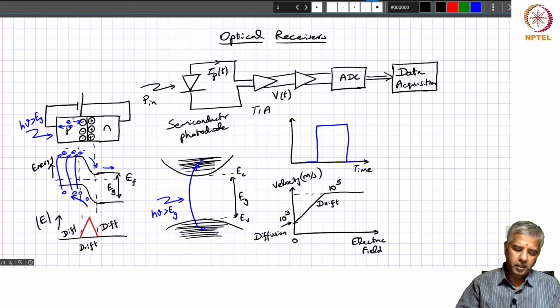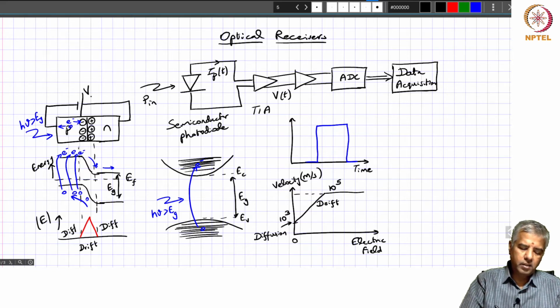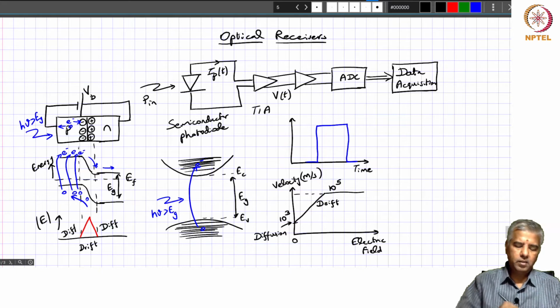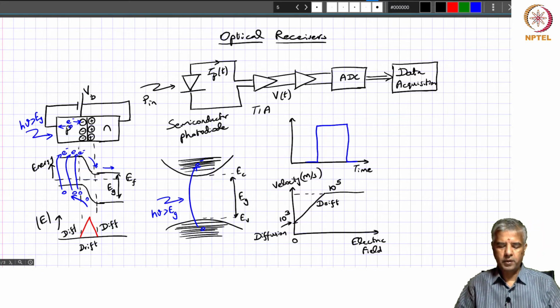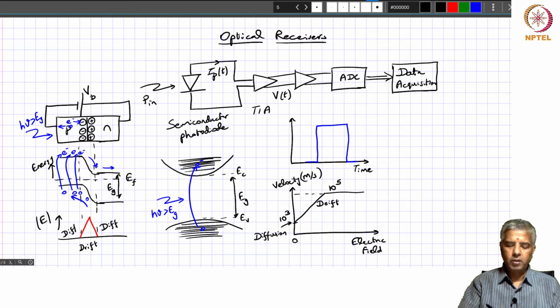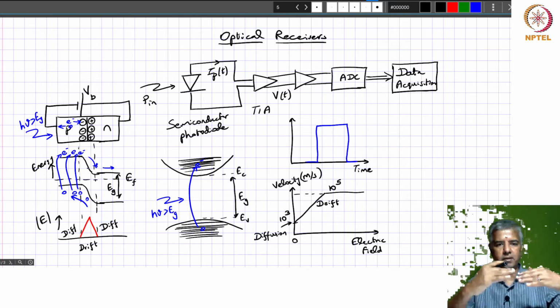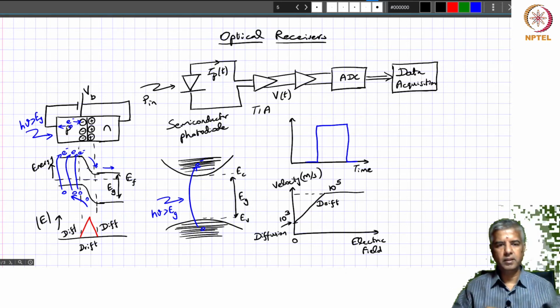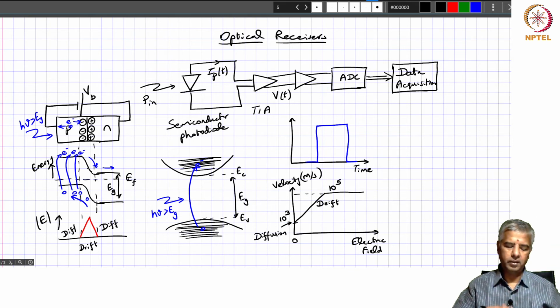And the key point here is, if you change your external bias, let's say this is VB, right? It's a negative bias, or a reverse bias, that we are providing. If you increase your reverse bias, then this electric field gets enhanced. Essentially, the Fermi energies are pried open, or displaced either side, and correspondingly this barrier is going to get enhanced.